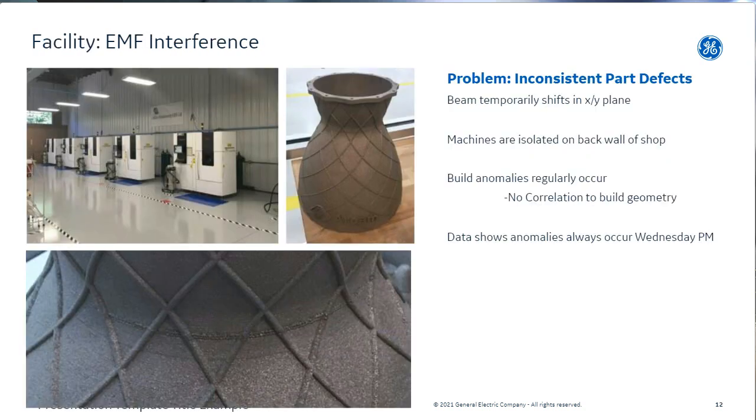EMF experience, yes. So, beautiful customer site here. 5 Arcam machines in a row. They're in the back corner of the shop. This shop happened to have a bunch of CNC equipment, so they're turning large 3-phase motors on and off. There's a bunch of EMF in the rest of the shop. They've got it marked out very clearly. Nothing massive or anything unrelated to EBM comes within the larger boundary in front of the machines. Then they've got one that's even closer, and that is no toolboxes, no cell phones, trying to really minimize it.